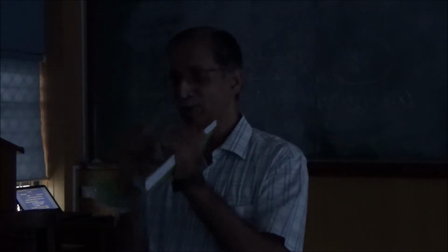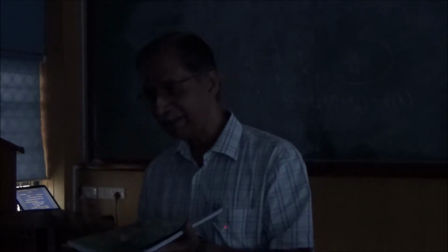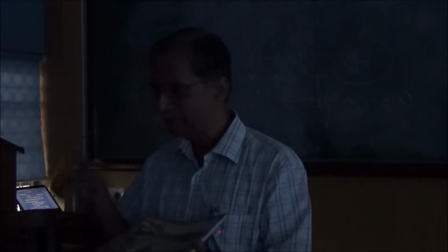No. Why not? Because if I apply a moment only on these two edges like this, it's going to bend theoretically like that. I can find the curvature. How do I get the curvature? For beams we talk of M by EI. But for slabs you have something called D with Poisson's ratio in it. Whatever it is, I get some curvature this way.